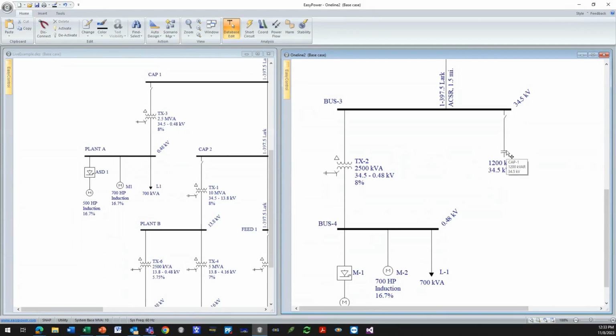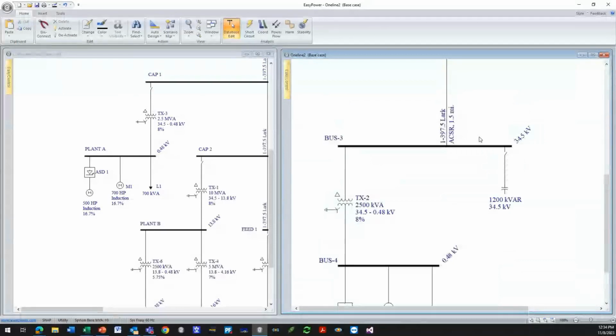Another interesting point. If you have no capacitor banks and you have no really super long cables that cause significant cable charging, you will have no resonant conditions. If you have no resonant conditions, then the distortion calculation you see up here will be due only to the upstream transformer impedance.